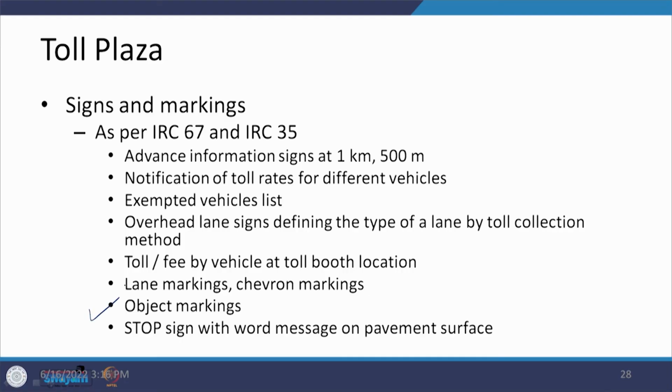Now, another thing which needs to be taken care of is the placement of the different signs and markings. We have seen some of the markings in terms of the object markings, in terms of the chevron markings which have been provided, or the lane markings which are being provided. There is going to be a stop sign, and one of the photographs we have seen also, which was placed just at the start or the nose of the island from the direction from which the traffic is coming.